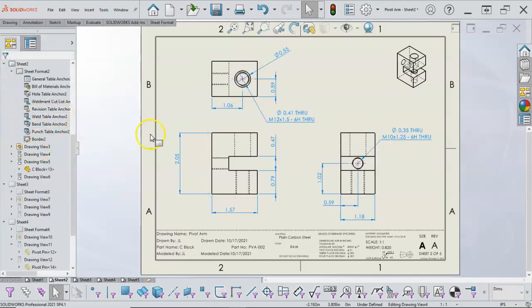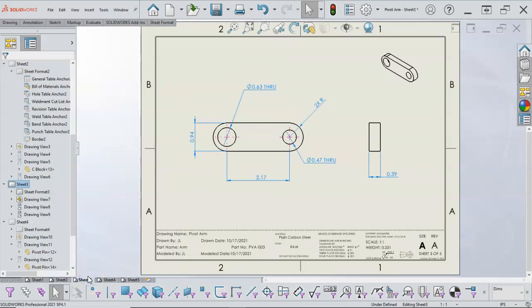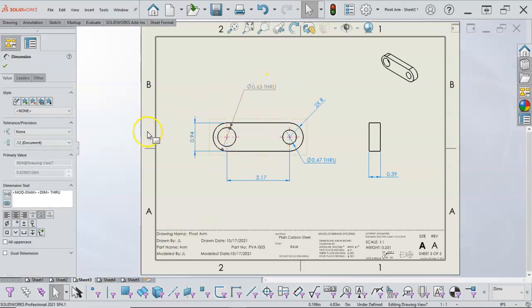All right, the next pass would be to do the tolerancing, checking for any items that we would want to hold a little bit closer. If two decimal places is good for most of these, which keeps it at stock material, the holes and through holes may want to go to three decimal places.